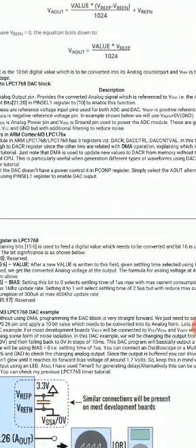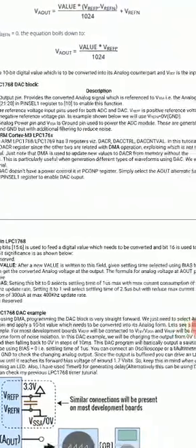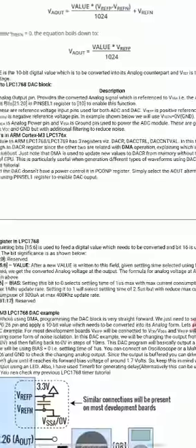Here we are using only DACR, because the other 2 registers are used with direct memory access operation, which is not in our syllabus. So we will be dealing only with the register called DACR. In this DACR we put the digital value and enable the DAC, and then it starts producing the analog signal.